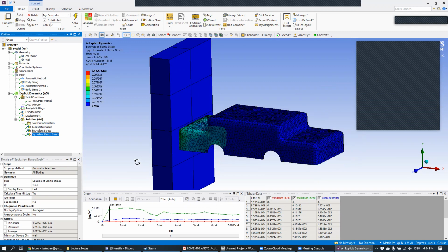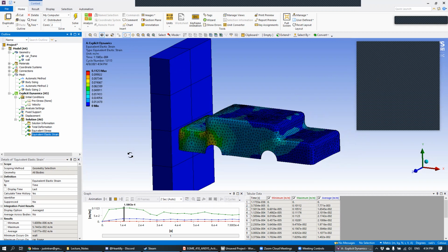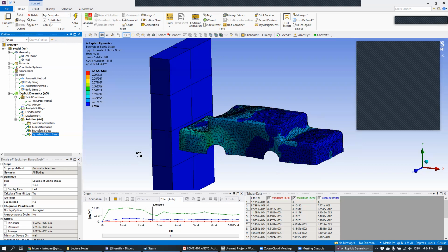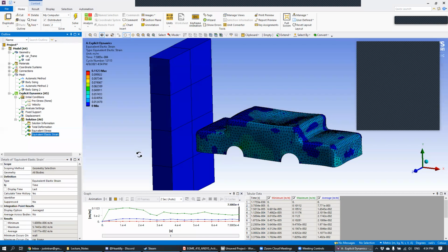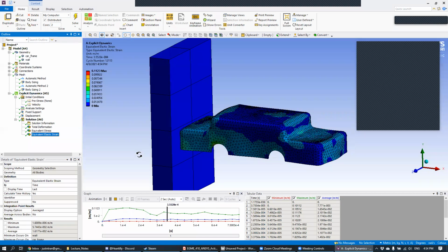All right. And yes, it looks like Jell-O, like a wiggly thing. It's because we assumed our material was perfectly elastic. But if we chose a nonlinear material or a buckling material, then the car would actually deform and stay like that.